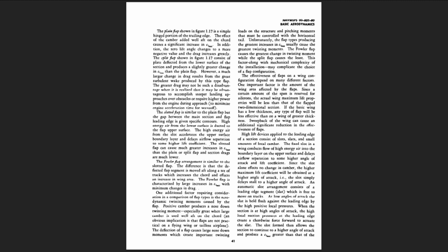The Fowler flap causes the greatest change in twisting moment while the split flap causes the least. This factor, along with mechanical complexity of the installation, may complicate the choice of a flap configuration. The effectiveness of flaps on a wing configuration depends on many different factors. One important factor is the amount of the wing area affected by the flaps.